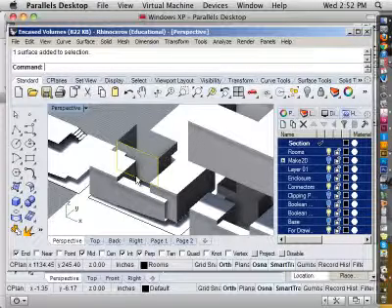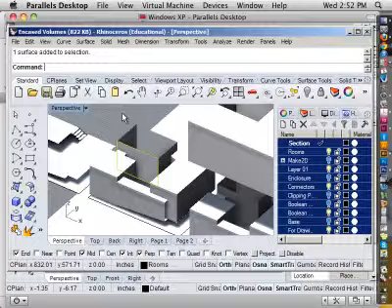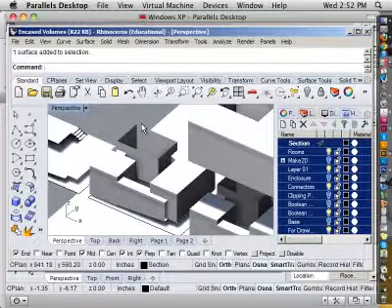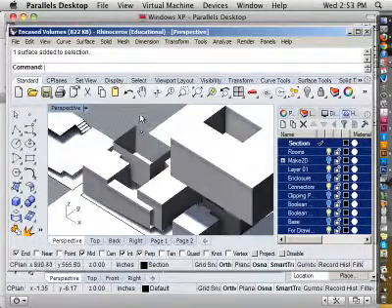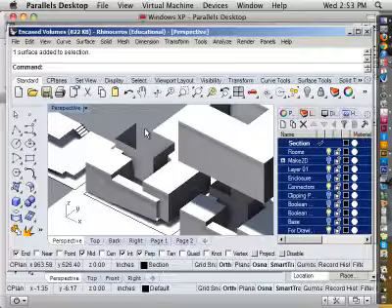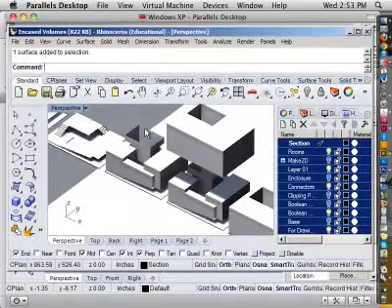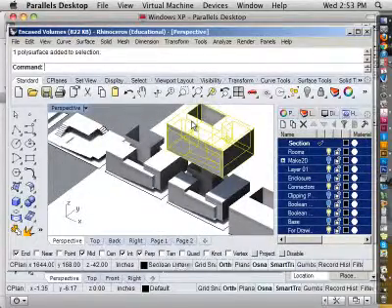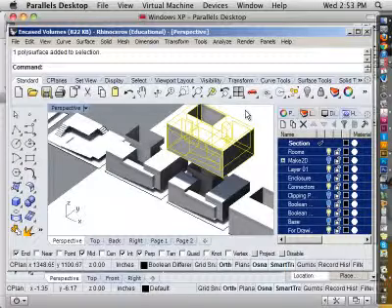If you don't, I think that was the problem that we were having up here, and so you can probably just use that Boolean volume for this purpose. If not, you can explode it and remove one of the faces if you are missing an opening or something like that. Okay, that makes sense. And then the box over top, that's just our model but shaded, correct? It should be, yes. It should be the enclosure of the model. Right.